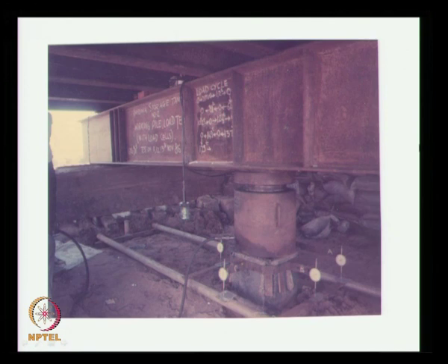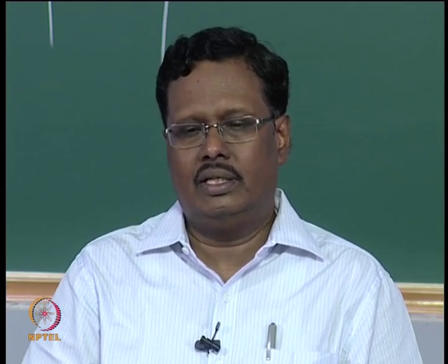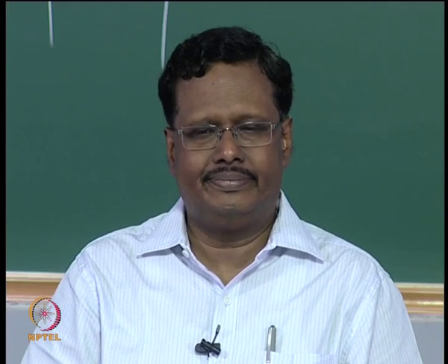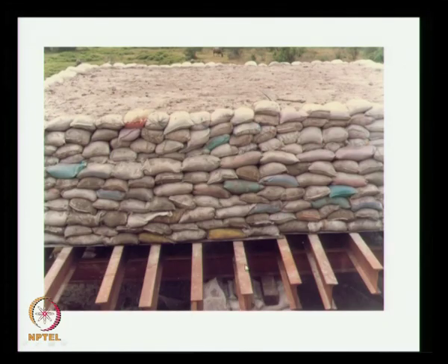It is purely a temporary arrangement, but this has to be done. Minimum 1 initial load and 3 working pile load tests are required to be done. So you can see the grillage here, you can see the sandbags inside. If you want, you can use loose sand also, no problem.